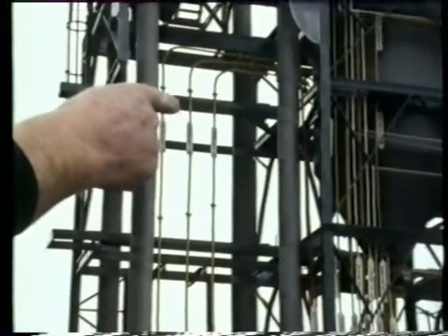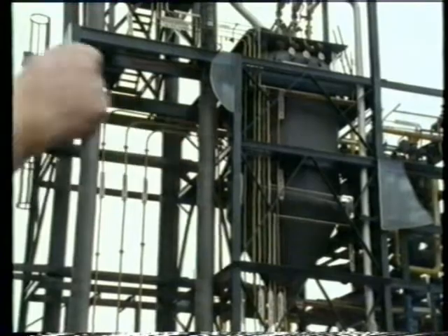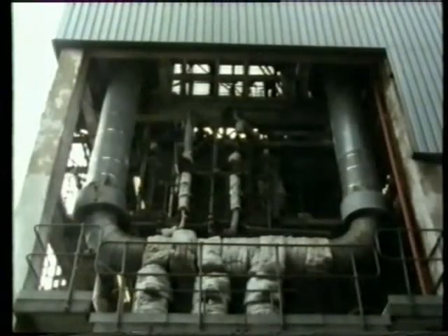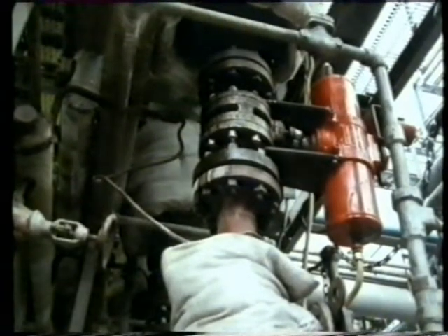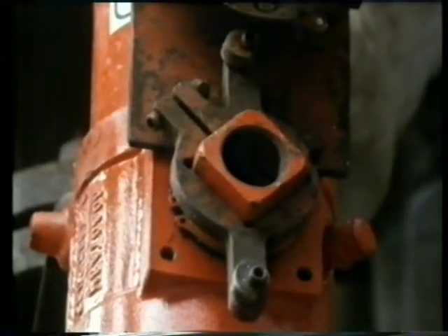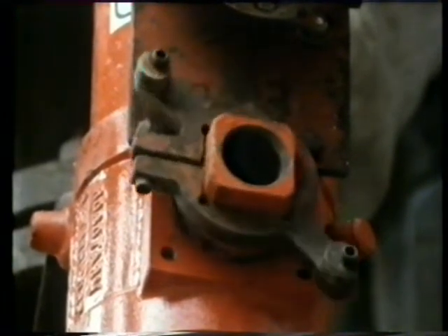There's a tank at the top called the flash tank. As the reaction proceeds, the pressure rises in the reactor loop, and there are 3 valves which work automatically, releasing polyethylene and carrier up one or other of the pipes leading up to the flash tank.